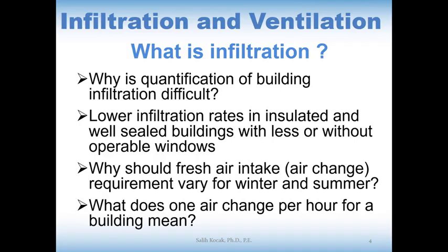And most of the time, if you go to Home Depot or Lowe's and look at the fans and the fan ratings, the fan ratings and heating and cooling formulas are always based on CFM values. So the air change rate must always be converted to CFM so that we can do our calculations and ensure that they are okay.